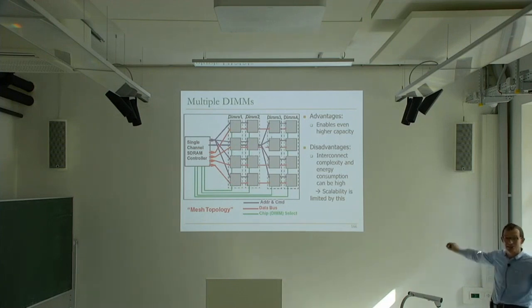That's the only interconnection that you have. So to be able to access memory that's over here, you need to go through the first DIMM, second DIMM, third DIMM, fourth DIMM, dot, dot, dot. And I believe they were proposing 8 DIMMs. So if you wanted to access memory that's far away over here, you need to go through 8 hops. So now you have completely asymmetric latencies in memory. So your performance depended very heavily on where your data is.